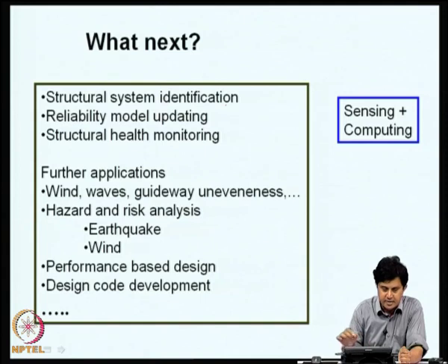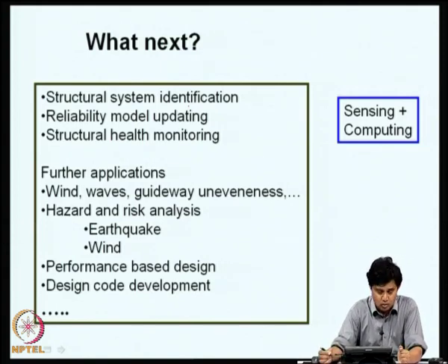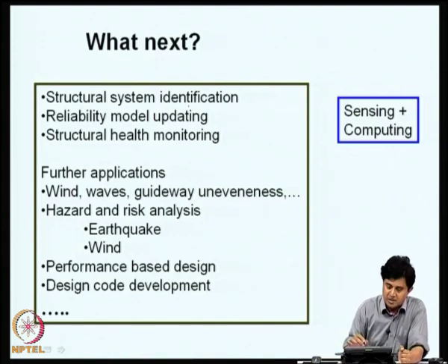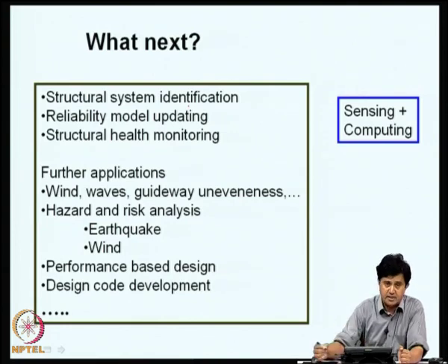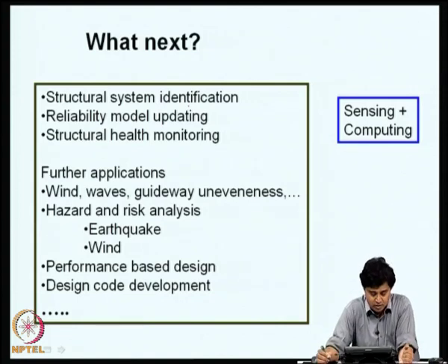In the area of structural system identification, we essentially study existing structures. An existing structure can be analyzed using mathematical models and also using experimental tools. So, the predictions from experimental and mathematical models often do not agree because of various idealizations, for example, made in mathematical modeling pertaining to boundary conditions, flexibility of joints, constitutive laws, damping models, etc. Typically in mathematical modeling, we make simplifying idealizations in treating these aspects.